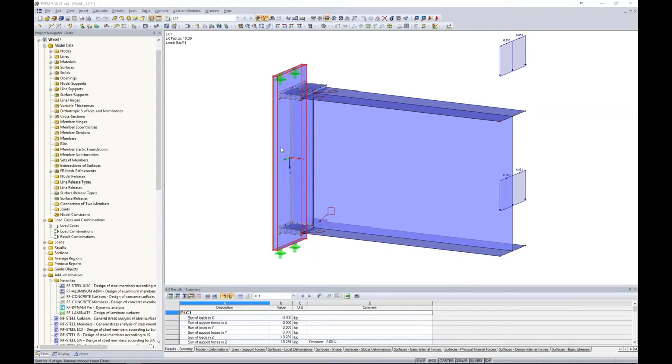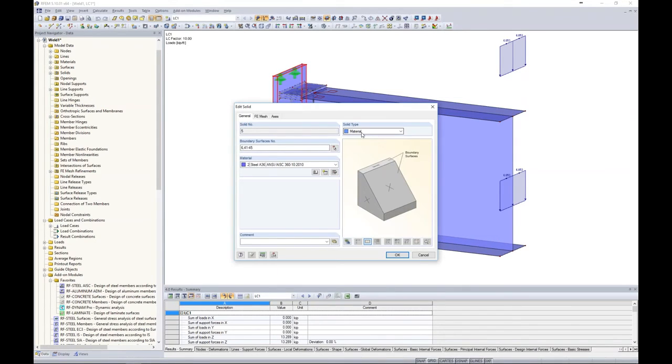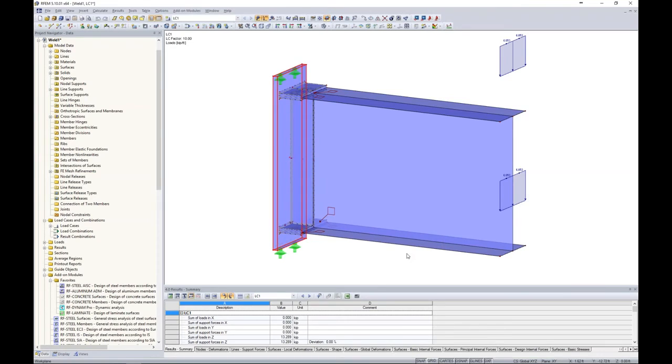Well, when I take a look at this plate element, I no longer change this to a contact surface or contact solid. It's just a typical 3D solid with a material set within the depth of steel A36. So this is just a 3D element within our program RFEM. Now, all of those requirements for boundary lines, same integrated objects, those go out the window for a typical solid element. That's not required for typical solids, just only for contact solids.